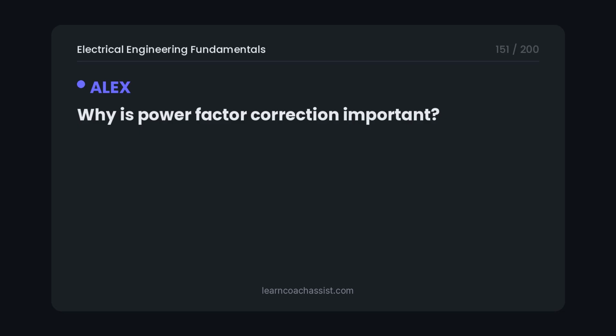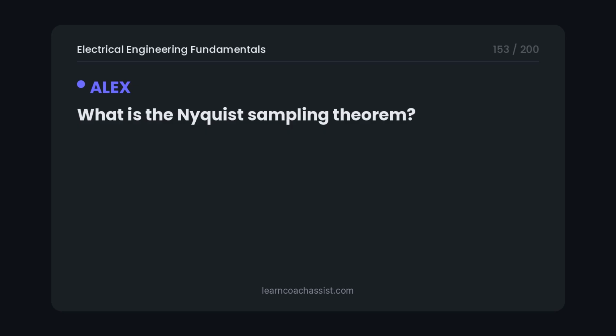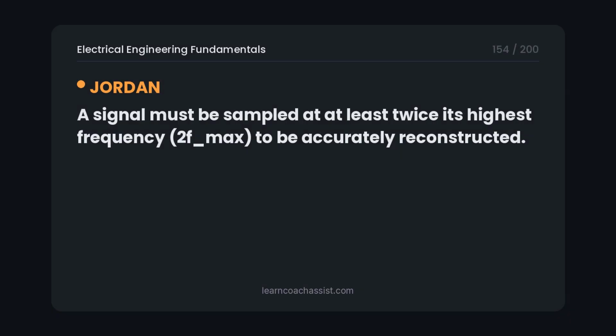Why is power factor correction important? Low power factor increases current draw and transmission losses. Correction, often via capacitors, reduces wasted energy. What is the Nyquist sampling theorem? A signal must be sampled at least twice its highest frequency, 2f_max, to be accurately reconstructed.